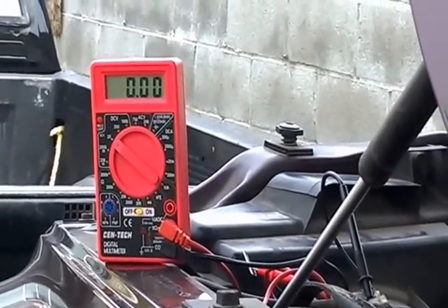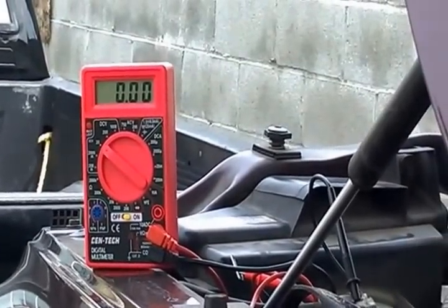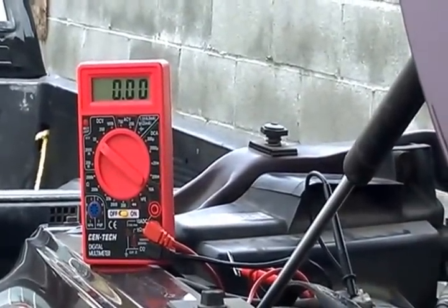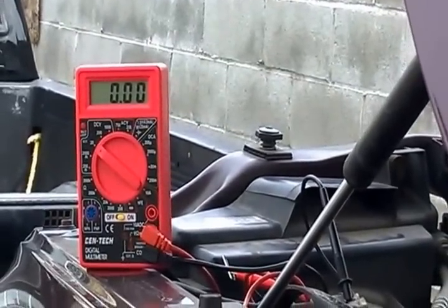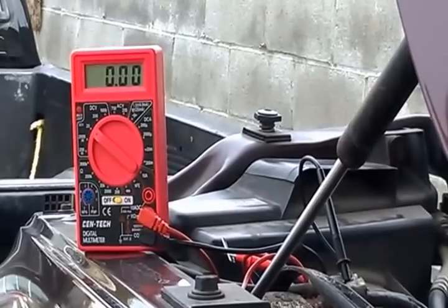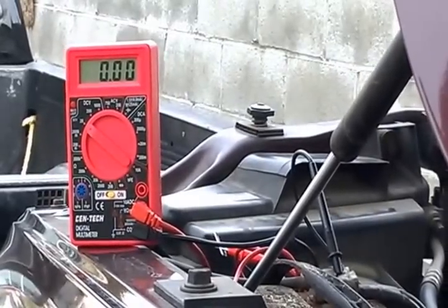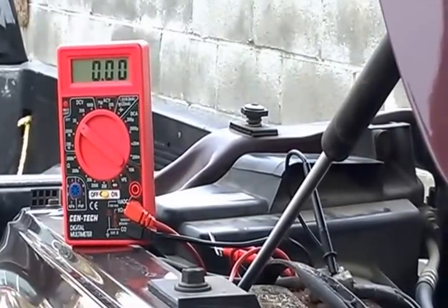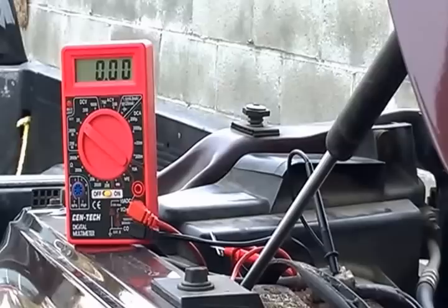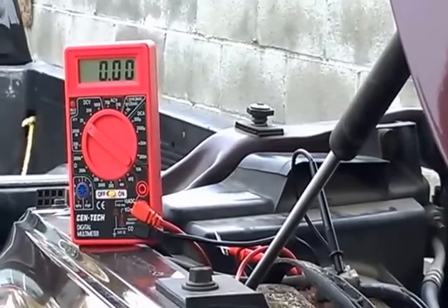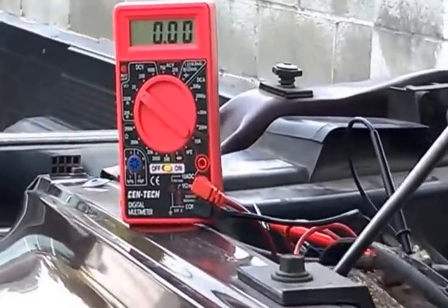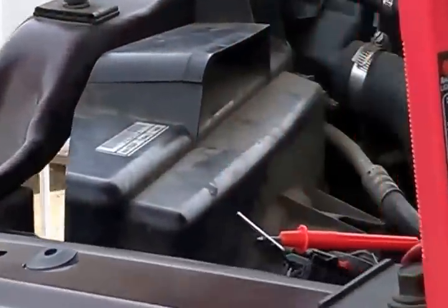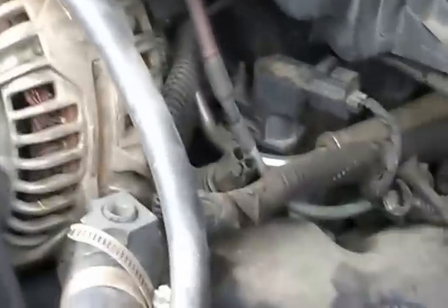As you can see, this voltage did vary, which tells us that this circuit is pulse width modulated. Which means that the ground side will also be controlled. So the voltage on the ground side will vary too. So next step is to go to the dark blue with brown.